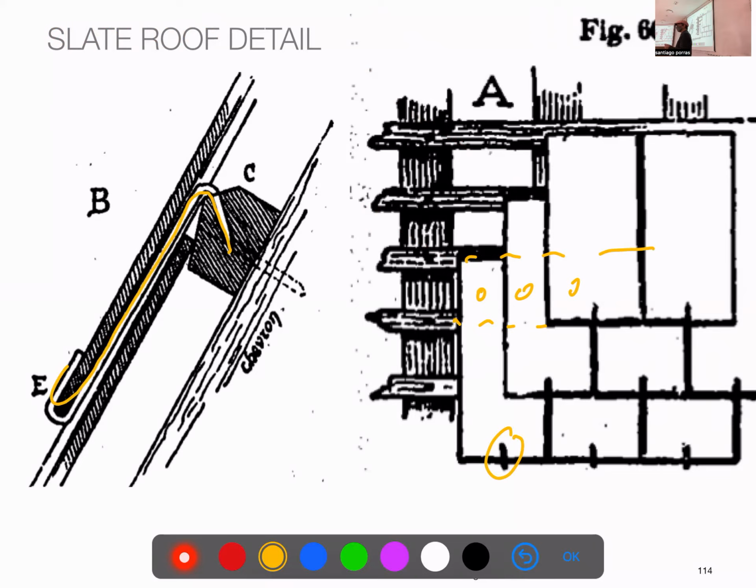I wouldn't say what is better. In my house, I have hooks. And after 20 years, they're starting to rust, even though they are galvanized. It's not nice. If they had nails, other slates would cover that, and probably that still would not be rotten, right? But with the nails, you break the slates and you perforate, so they are more fragile.